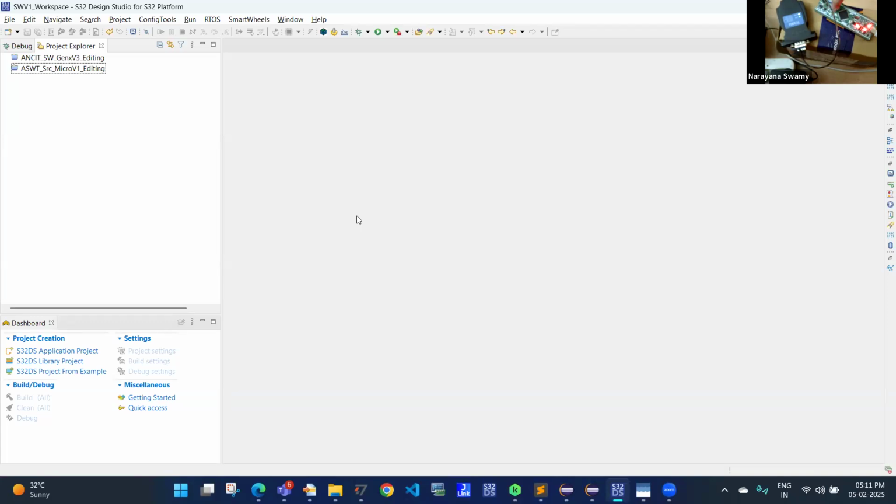Maybe the LED is here. So if I press the switch, the LED should switch on. If I have to make this, the first thing you have to do is debounce. They are mechanical switches, so there will be noise on the switch. So you have to write the code for debouncing. Then you have to write the code for driving the LEDs. Maybe it's a simple code, but you have to switch it on and off.